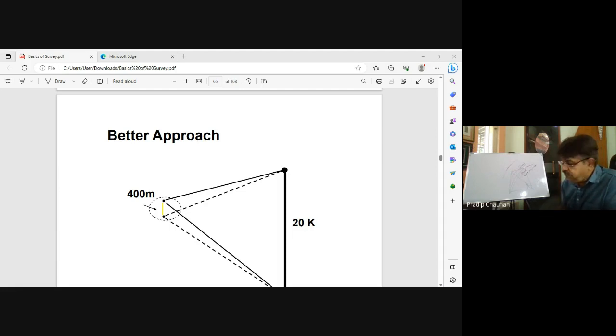elevation. See, if you are moving at a certain speed, what will happen? At speed, there are centrifugal forces and centripetal forces. One is attracting towards the center, and another is taking your vehicle away from the center. So those forces need a certain slope of the road, cross slope, a camber, reverse cambering. It is known as super elevation, and it is applicable for road, rail, everywhere, all vehicles and everything which is moving on the surface of the earth. So then survey has to be done accordingly.